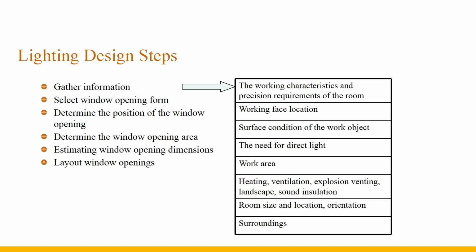Control the area of the north window of the northern heating building and the area of the west window of the northern building to reduce heat loss and west exposure. For the room where there is a lot of dust and waste heat indoors, separate ventilation openings should be set up, and keep a certain distance from the lighting openings to avoid contamination of the lighting openings.